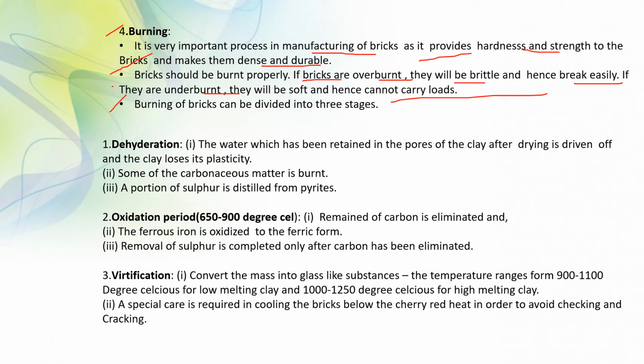Next, burning of bricks can be divided into three stages. Number one, dehydration. The water which has been retained in the pores of the clay after drying is driven off, and the clay loses its plasticity. Then some of the carbonaceous matter is burned. Next, a portion of sulfur is distilled from pyrites. Number 2, oxidation period.